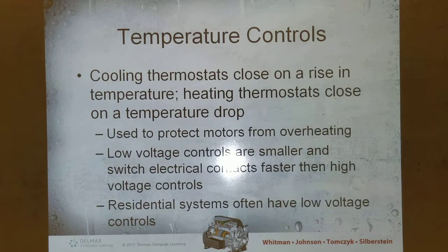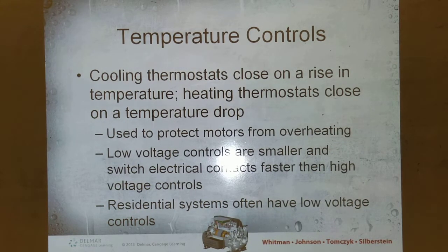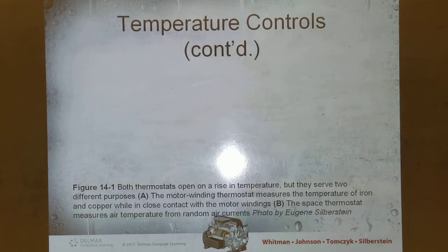Temperature controls: cooling thermostats close on a rise in temperature, heating thermostats close on a drop in temperature. Used to protect motors from overheating. Low voltage controls are smaller and switch electrical contacts faster than higher voltage controls. Residential systems often have low voltage controls. Temperature controls continue.